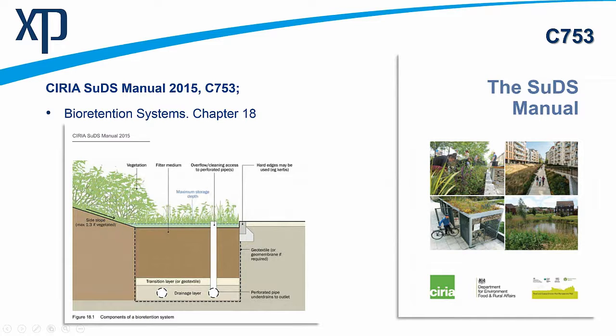And this has been used a lot, particularly in the retrofit industry, which is why I'm going to focus on this particular aspect during the webinar today. So the water forms this shallow depression. It's really great for regular rainfall events. Within the UK, for example, the majority of the rainfall events are less than 5 millimeters in depth. So often that water will be taken up by the vegetation, sit on the surface, and often just evapotranspirate away.